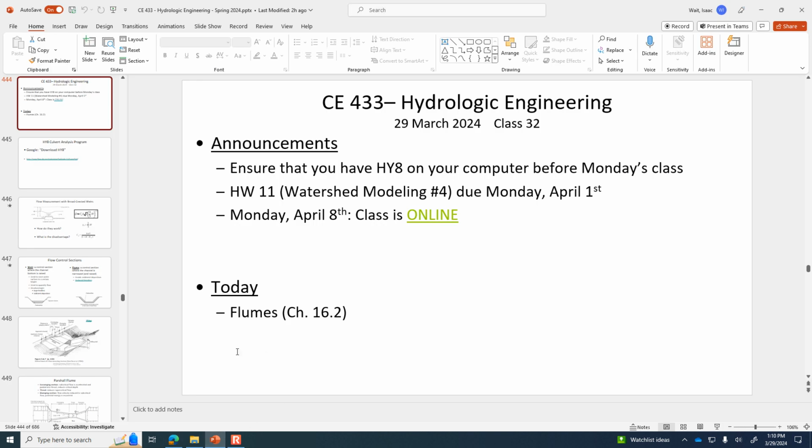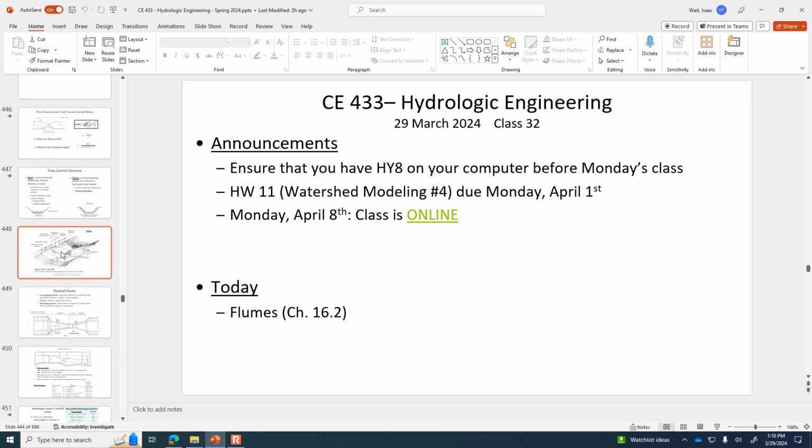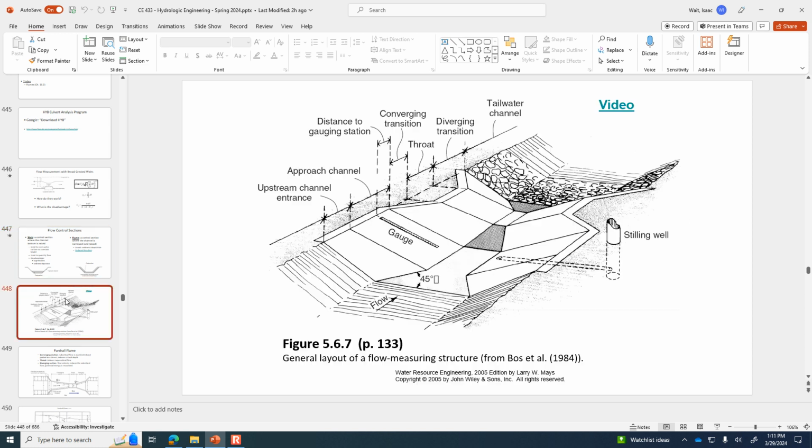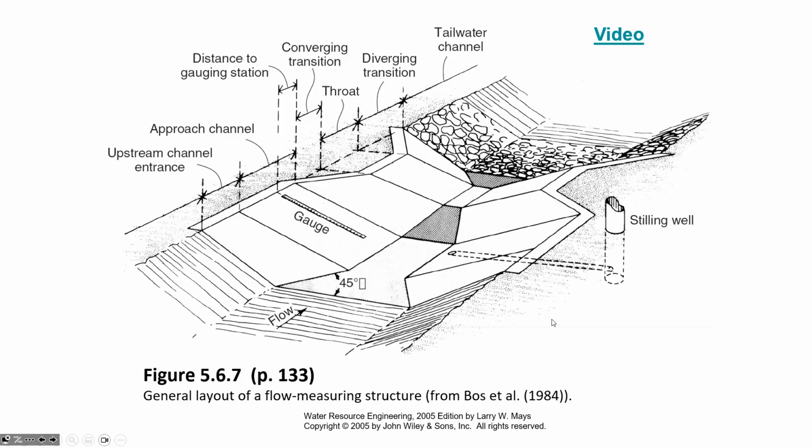So that video mentions two of the primary advantages of a Parshall flume, one being that there's a wide range of flow rates that they can be sensitive to, and that the calculations are relatively easy as well. Prior methods of quantifying the flow rate, with flumes that didn't have the downward slope in the throat, required more than just two measurements. Now typically in a Parshall flume, you're just measuring the flow depth at two locations, and then the empirical equations, which are calibrated to tell you the flow rate, are just based on those two depths.